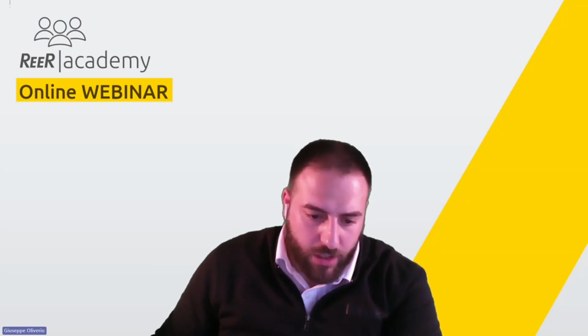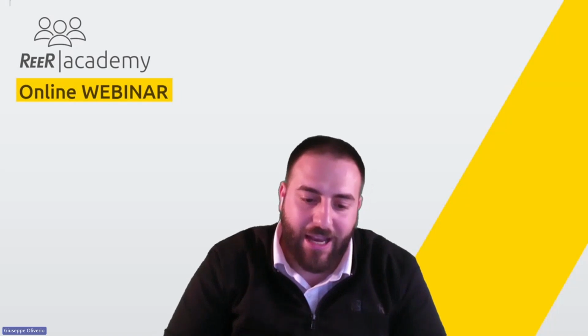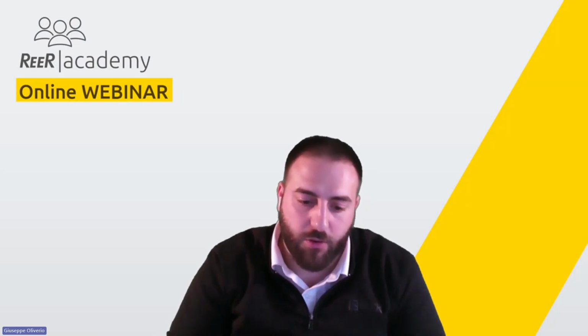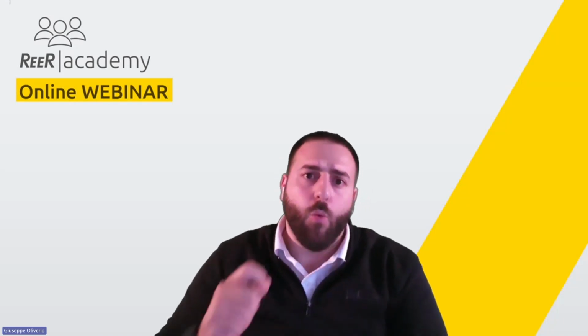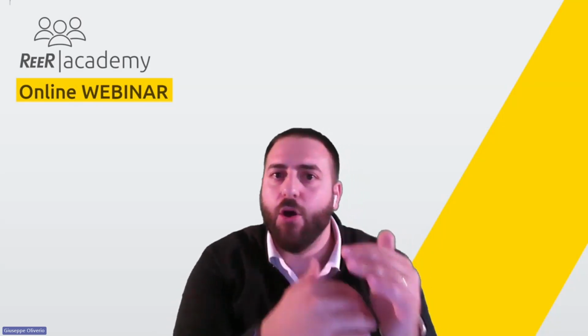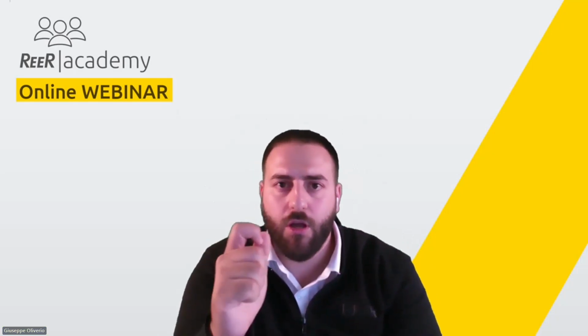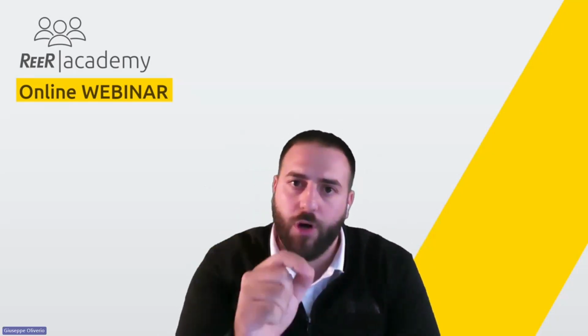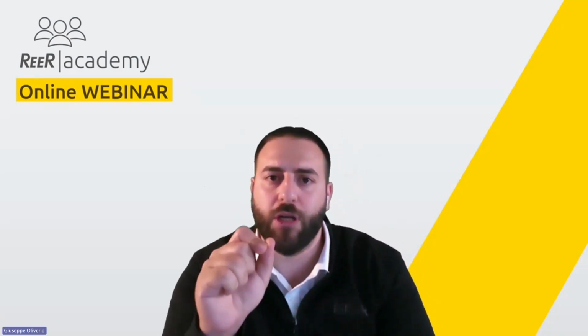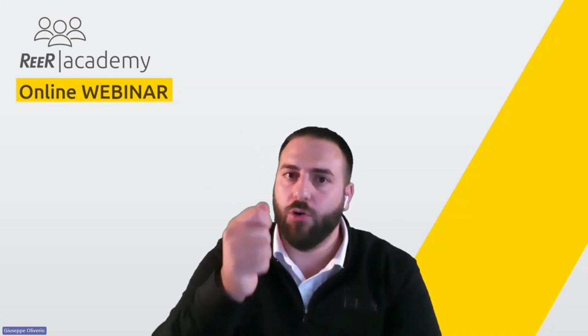Okay, one question. If I have more than one M1S COM in the network, can I select the connection for download and upload? What you can do is to do the device scanning, and by knowing the MAC address, then you can choose where to download and where to upload. You cannot do it by clicking on the download, because in order to download or upload, you must be connected.